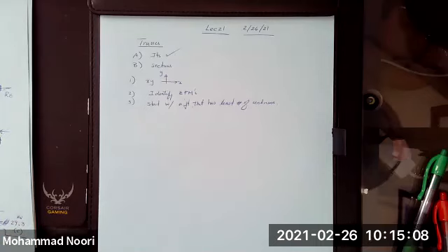And as you notice, of course, intentionally, I never mentioned that you have to find the external reaction forces first. You don't have to. The general procedure is that you start with a joint with minimum number of unknowns. All right. Any questions?